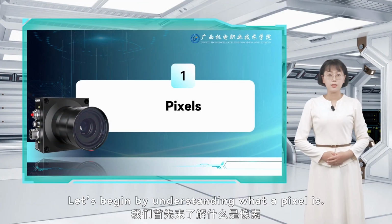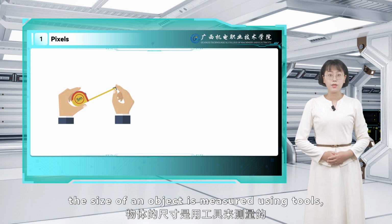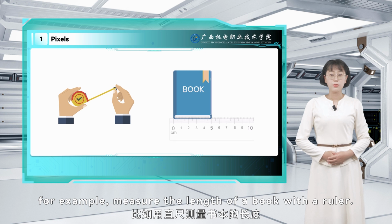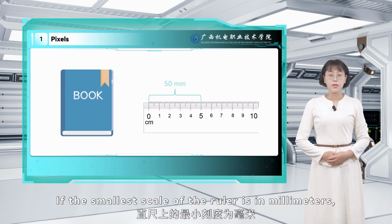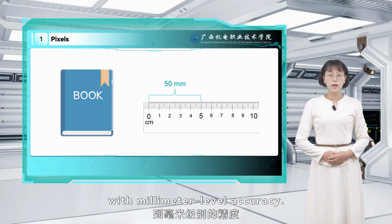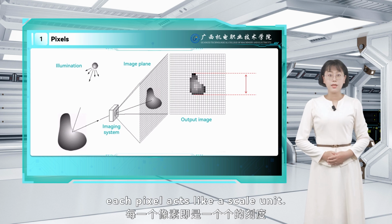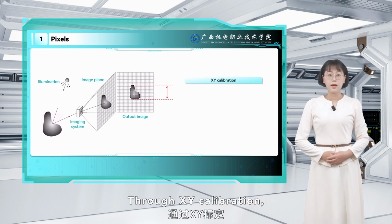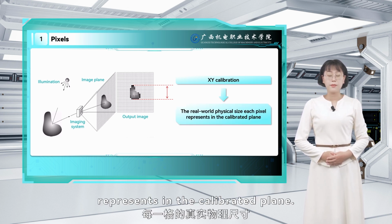Let's begin by understanding what a pixel is. In everyday life, the size of an object is measured using tools. For example, measure the length of a book with a ruler. If the smallest scale of the ruler is in millimeters, we can read it to measure the object's length with millimeter level accuracy. In vision systems, each pixel acts like a scale unit. Through XY calibration, we can determine the real-world physical size each pixel represents in the calibrated plane.